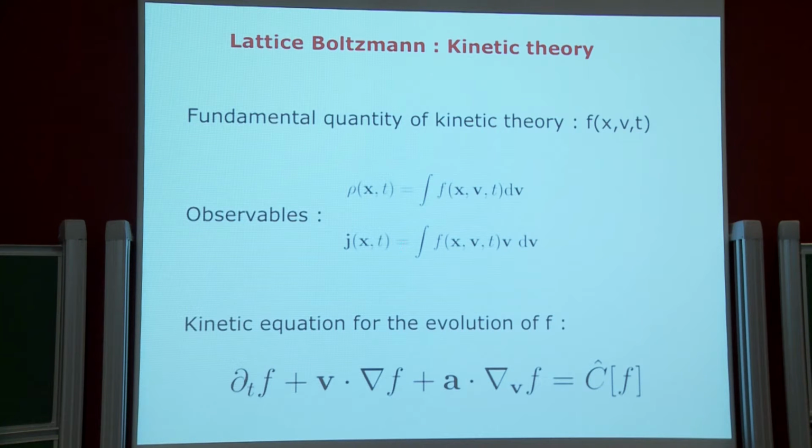what you get is the mass flux, or the flux, that is the number density times the velocity. But if you have here a mass density, you have a mass flux here. You can do the same thing for the second moment. So take the integral of f v v dv. So that will be a tensor, and that will be the stress tensor. And you can also introduce other moments of this probability distribution function that will give you the energy density, temperature, energy flux, and so on.